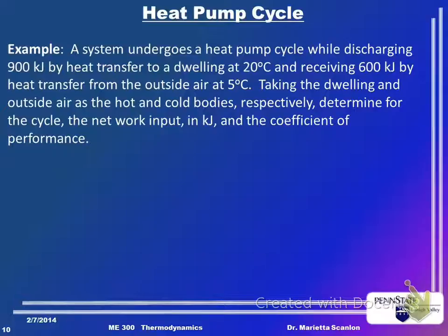So heat pump cycle, you know what you expect for your work. Discharge 900 kilojoules of heat, receive 600 kilojoules. Find the net work input and the coefficient of performance. So again, another straightforward plug into the equations. Can the coefficient be negative? No.